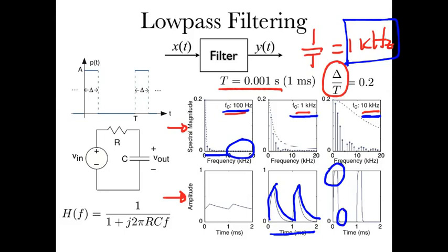So it doesn't filter very much, but if the cutoff frequency is really low compared to the first harmonic, you get a lot of change of the output. And this is a common use for low-pass filters, to change the waveform to be something that you want, given some very simple waveform that you could probably produce in the lab.